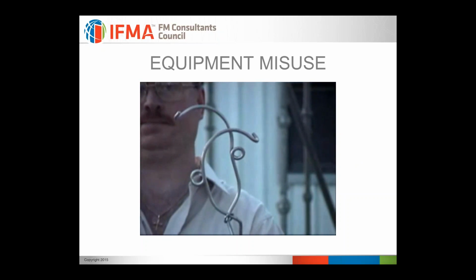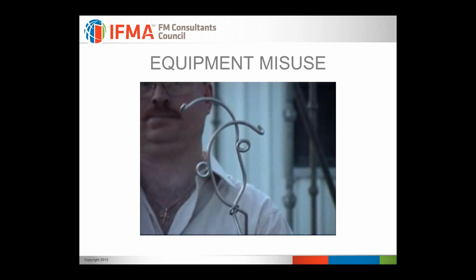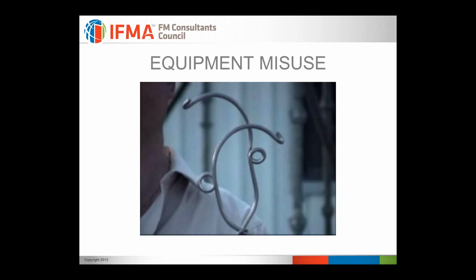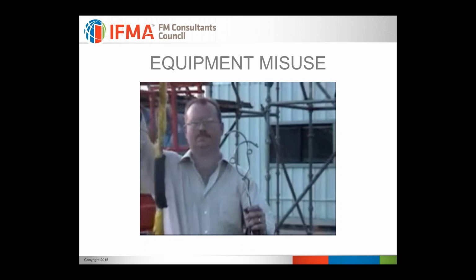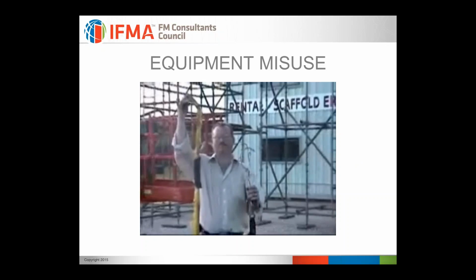The reason this test was done is because not too long ago there was a fatality with somebody who was using a clamp just like this in a manner very similar to what you just saw in the test. They were climbing a tower, and although the person was working alone, so we don't know for sure, the evidence points to this person having this wire clamp connected at the intersection of two members, and it side-loaded those wires and caused a failure very similar to that, and that person fell to their death.